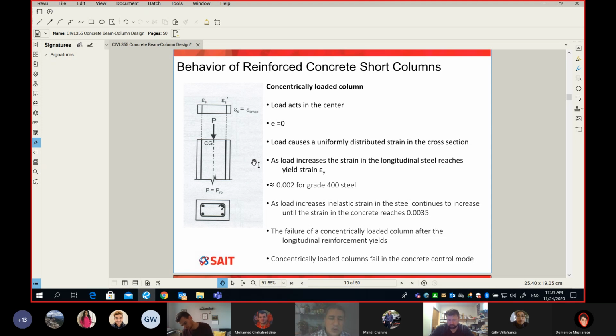Now, in the next chapter, we looked at shear, so we replaced the M by V. V sub R became the shear capacity of your beam, and V sub F is the factored shear applied to your beam. In this class, what are we using for axial load? The axial load is P. We will use the letter P for the axial load, so you will see P sub R and P sub F as well.